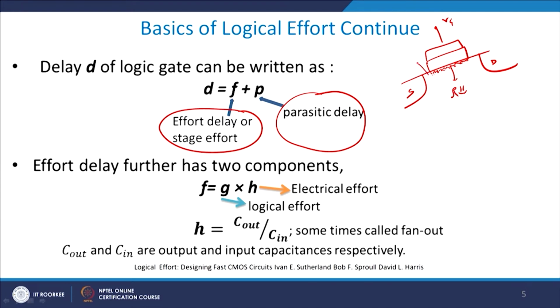But you see, if you look at this region also as an underlap region, these two regions, as well as this, then typically in these two regions you will automatically have a much higher delay, or the intrinsic delay will be larger, because there are no charge carriers here, and therefore this will act as a parasitic, which means that it is basically adding.